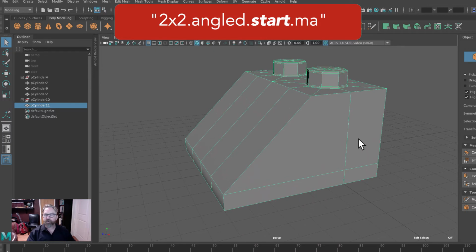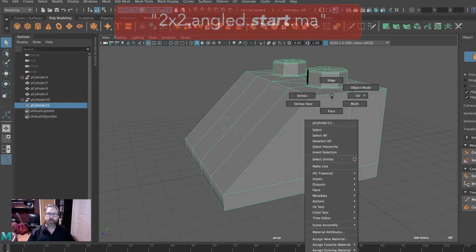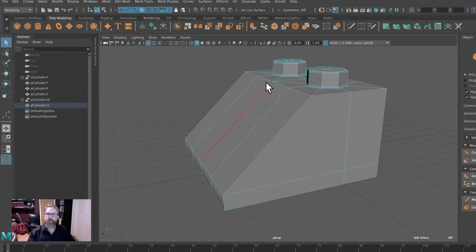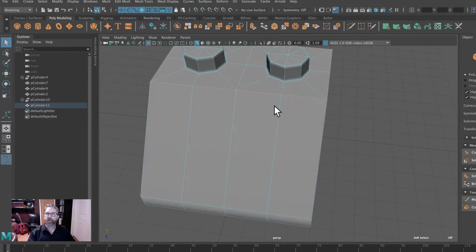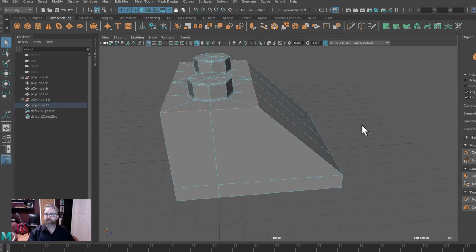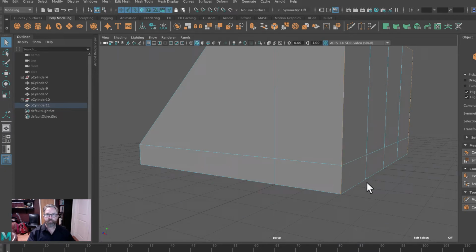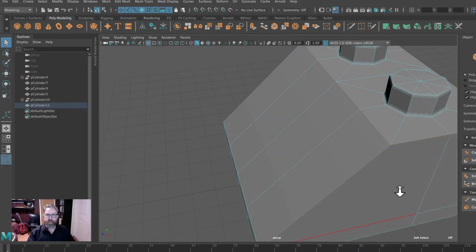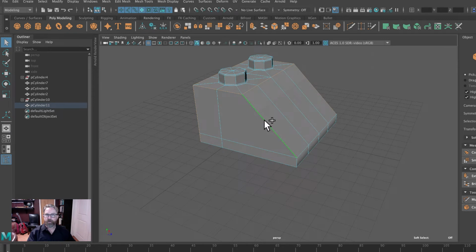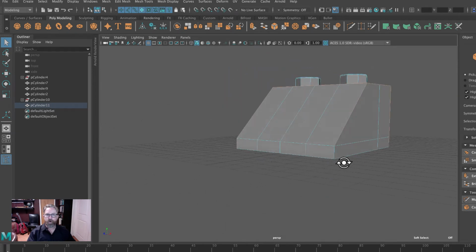And let's just go through the process of beveling this one. So we'll double click, shift double click, so we have that top rectangle. And let's just go down. We're not going to double click here because it would run up to the peg. We'll get the 2 edges on the back. We'll get this diagonal edge here. We'll get this corner edge. We've got 4 across the front.